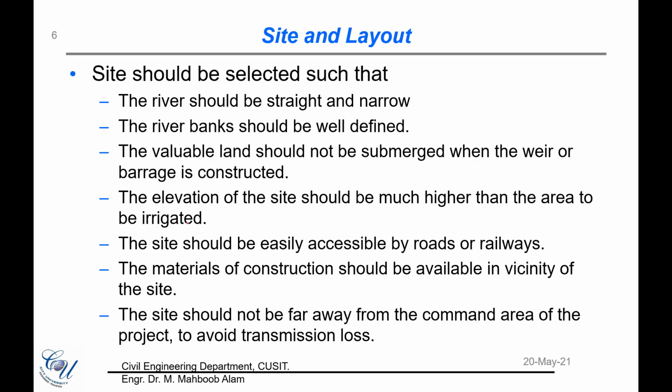The higher the elevation is, more energy would there be in the water. Both the hydraulic grade line and the total energy line would be greater, and it would be kind of easier to transport water to even the most further part of the catchment or to the area where it is to be transported. It is also important that these areas are readily accessible by roads or any other kind of communications.